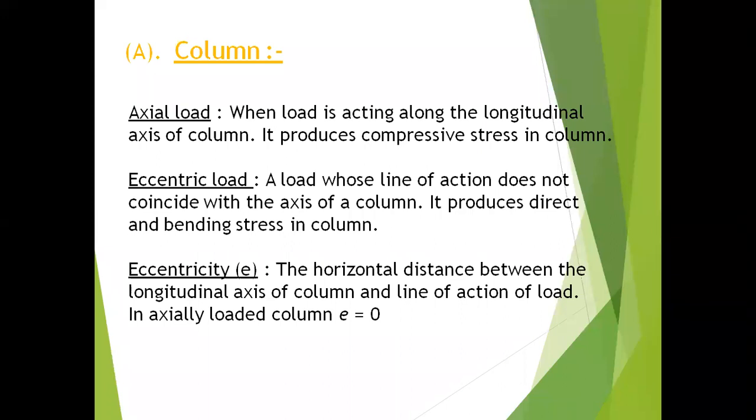Okay, ante the load is not at the center. The load is away from the center, right? So that load we are considering as an eccentric load. So by considering this eccentric load, we are able to analyze the column not only for direct stress but also for bending stress. Why? Because eccentric load makes the member bend.